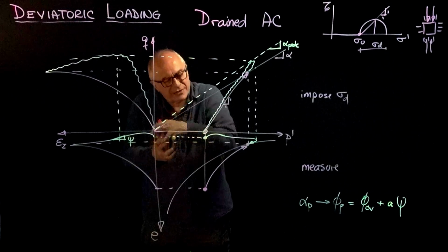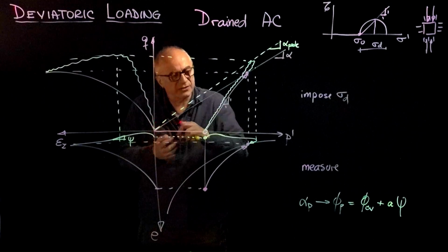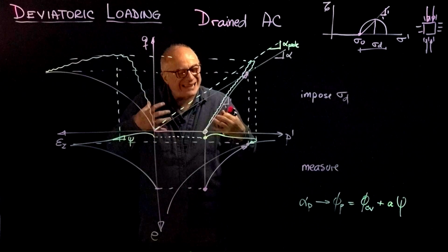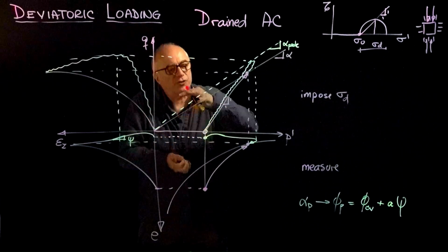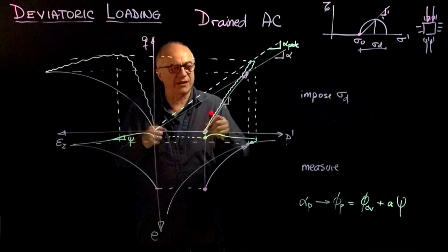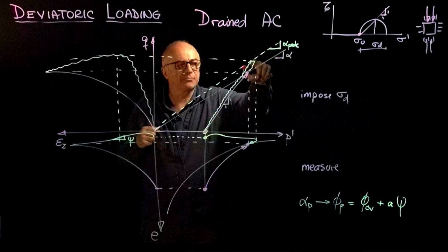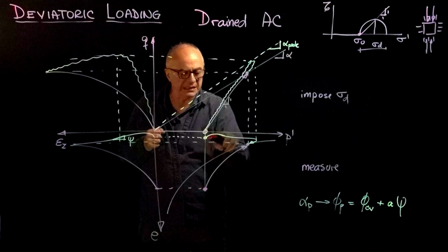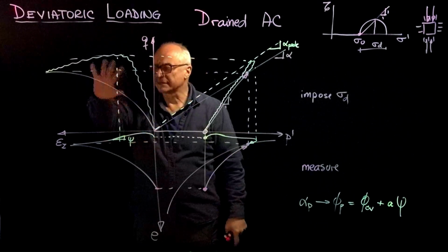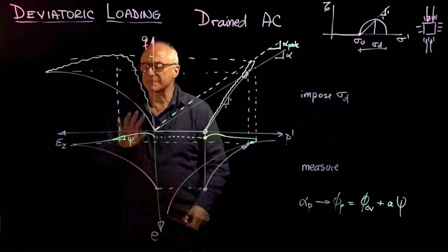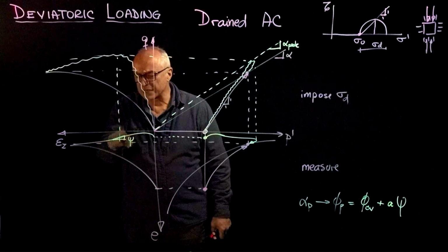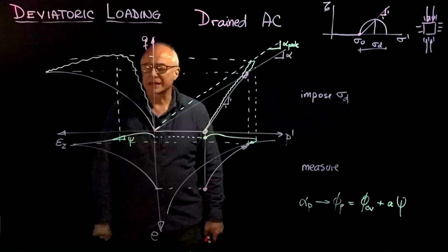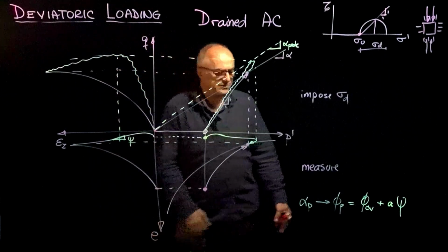Particles have to climb over the particles in front of them. So there is a volume dilation that takes place. You have to add energy demand, not only for friction, but also for volume expansion. You are working against the confinement. And so it gives you higher strength before it returns to constant volume shear. There is a little bit of contraction at the beginning and then dilation, and that completes the plot. Once again, I highlight that at the maximum rate of dilation is where dilation is contributing to constant volume shear, so you have a higher strength that gives rise to this equation.